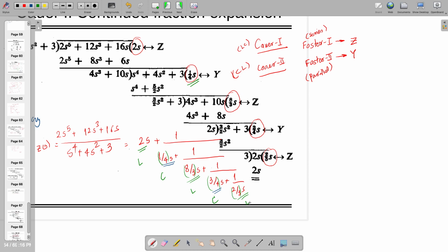When you are drawing this L, remember for an impedance function, if we have a plus sign, the first entry and the second entry will be in series. But next is a capacitor, and the next entry should be in shunt because this is a plus entry for admittance. So inductor, right?